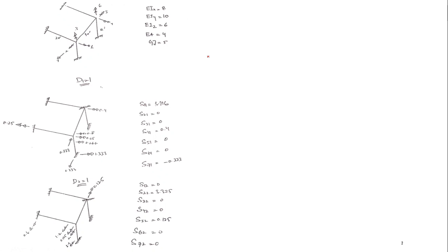For this frame, I have Ki equal to 6j minus r. Number of joints: I have 1, 2, 3, 4, 5, 6, so 6 joints. And number of support reactions: 6, 6, 6 and 6, so I have 24. So it comes out to be 12 degrees. But in this question, it is given that you have to ignore the axial deformations. To ignore the axial deformations, you have to subtract the number of members. So I have 1 member, 2 members, 3, 4 and 5 members. So I'll subtract 12 minus 5 and I'll get 7 degrees.